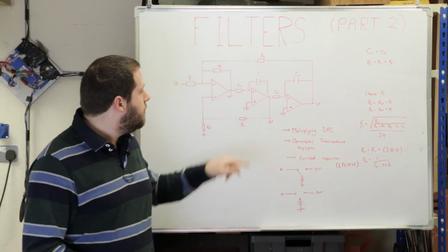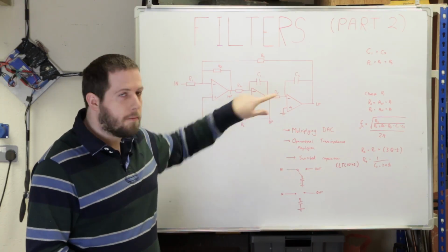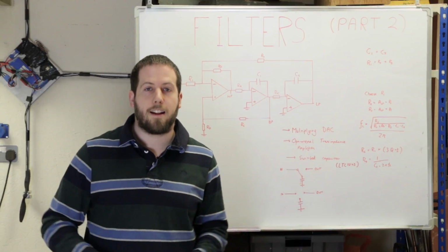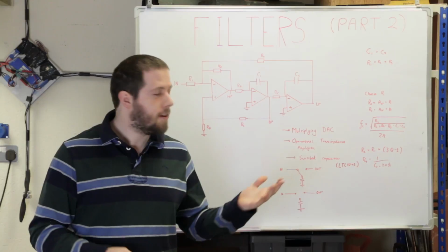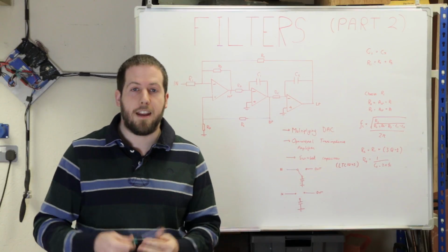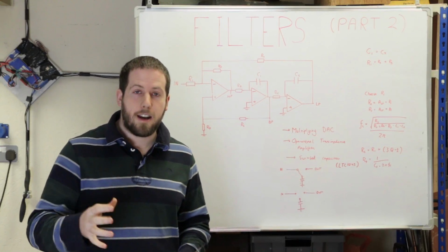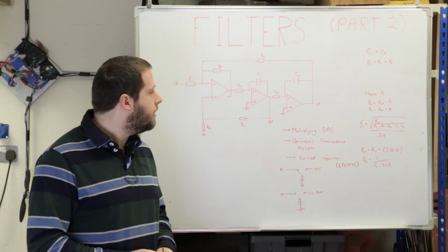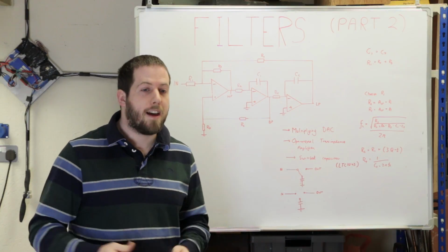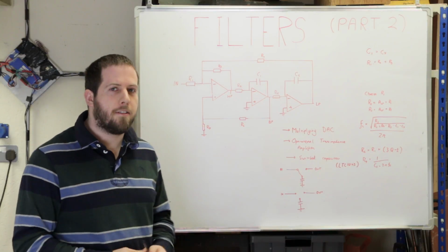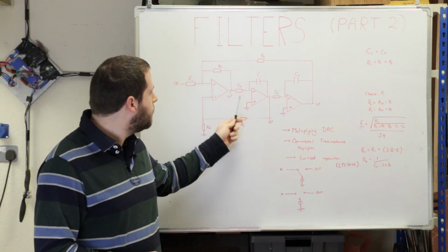The nice thing is you know the digital number going into both sides is going to be exactly the same. There are some tolerance issues with MDACs. It's not that bad and it is workable around, and it's a really interesting, quite viable solution. They're also not that expensive and cheaper than analog multipliers.